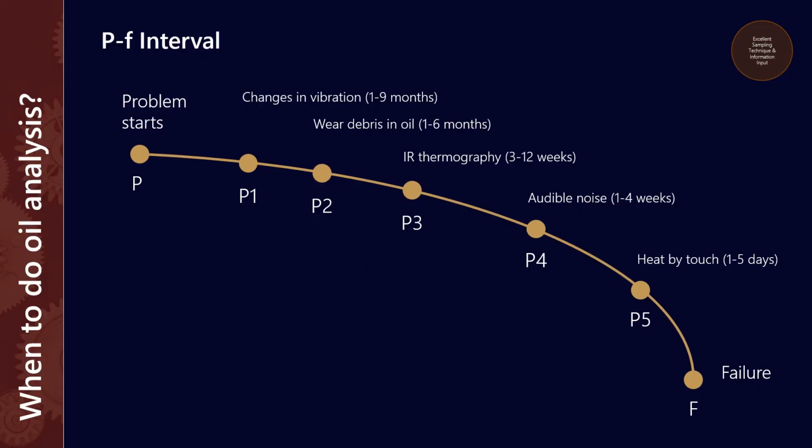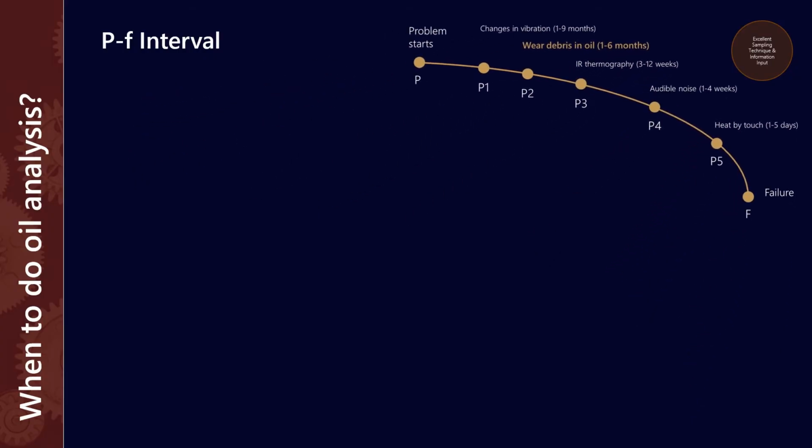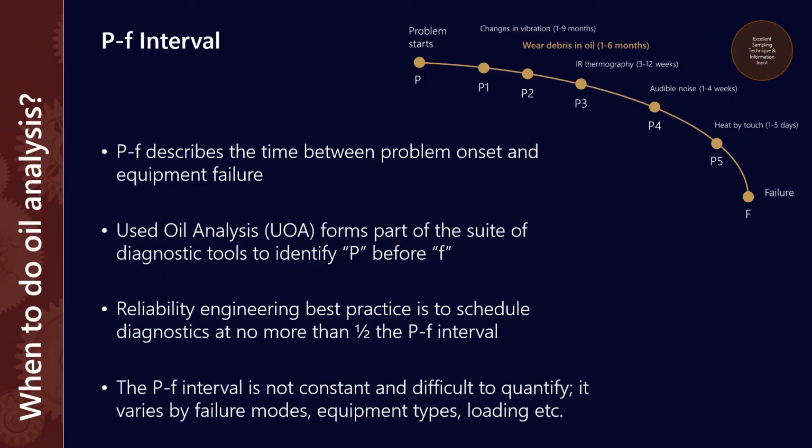So where does used oil analysis fit in? Well, obviously we can look at wear debris in the oil. That's one of the things that we can assist with. And so it's really important to understand this concept and to know that with reliability engineering best practices, we want to be scheduling our diagnostics at no more than half this P to F interval.